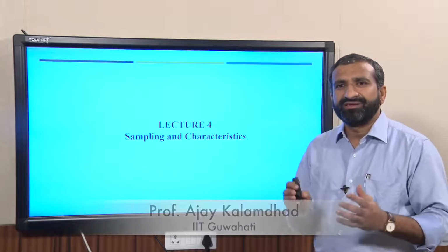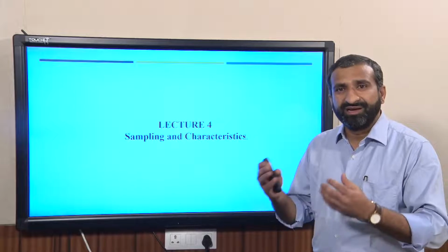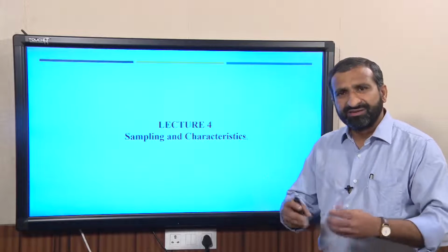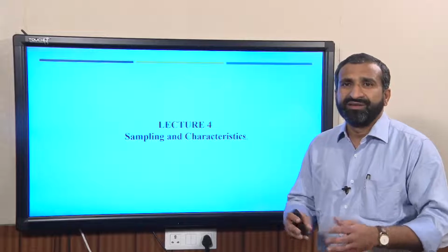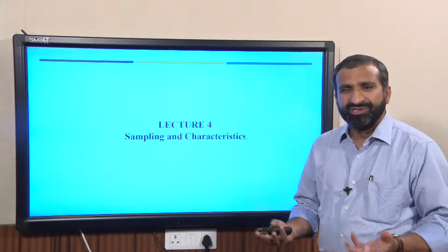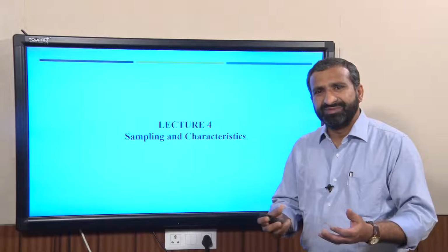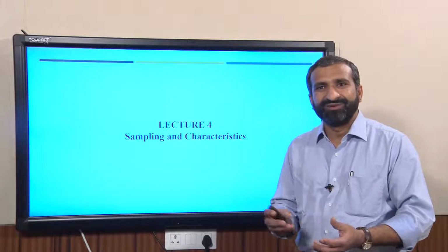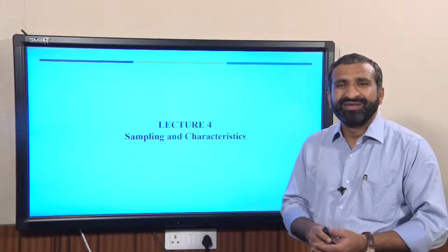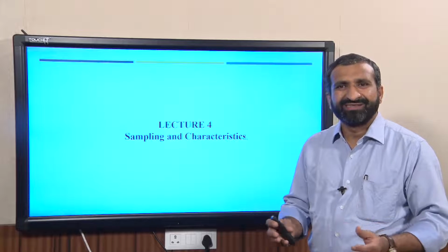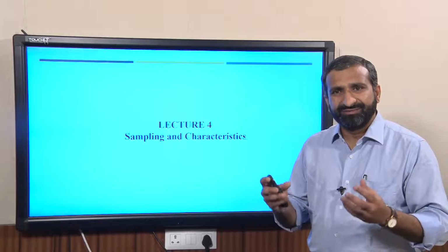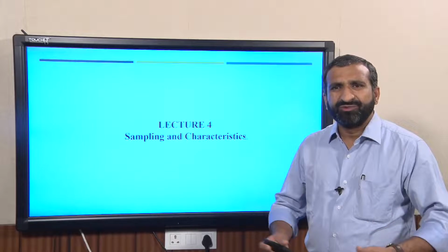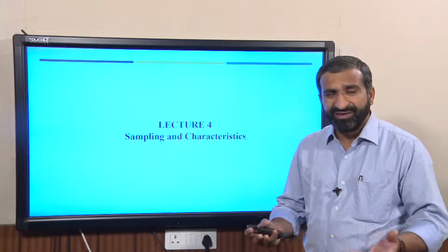This is the most important discussion before collection, treatment or disposal. Characterization is very important, and along with it, sampling is also very important. For water and wastewater, we need not understand much about sampling. Most students in colleges take a drinking water bottle to collect water or wastewater, because it is homogeneous in most cases. If you collect water or even wastewater samples from different areas, most of these are homogeneous and very easy to collect.